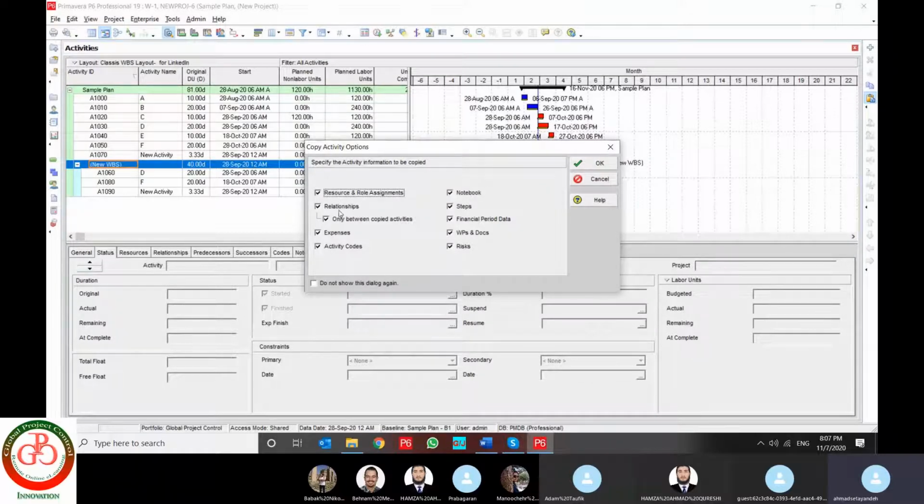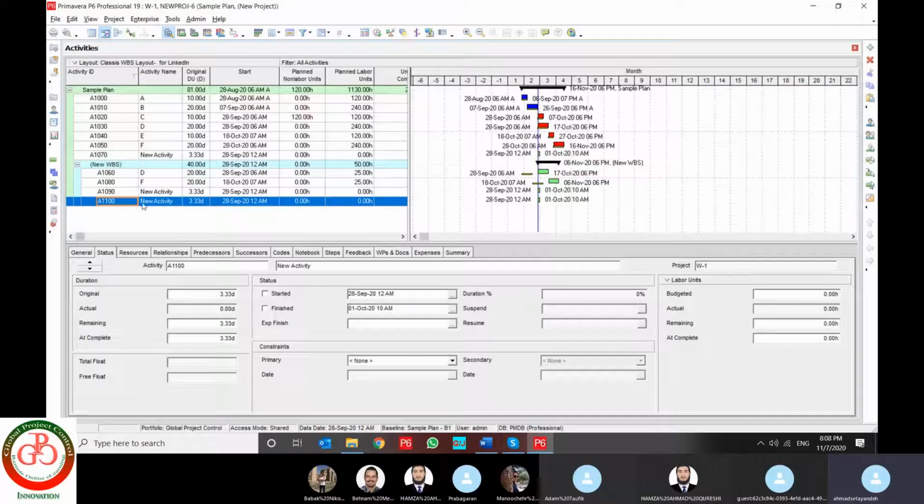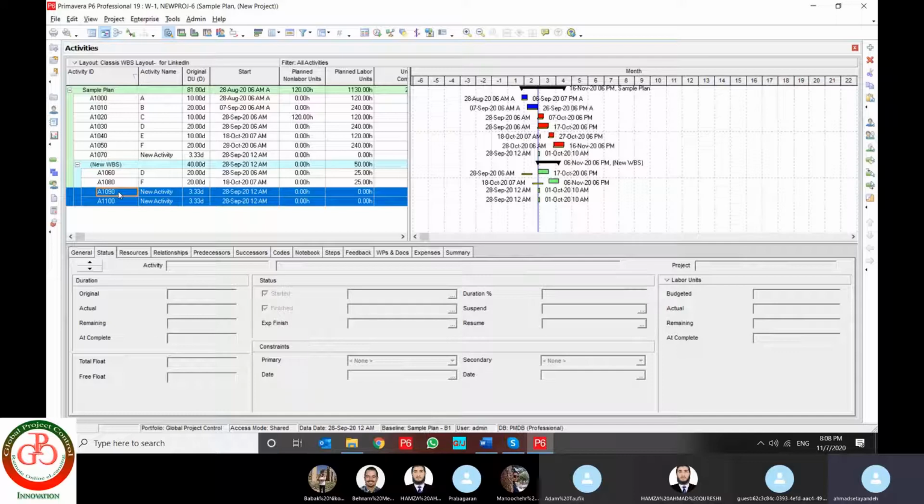If all settings are the same, you should use all these check marks. Then it asks you about renumbering activities, and that's it. Okay, also you can use select. I push Control in order to select two activities at the same time, and use delete. Then the software deletes my activities.